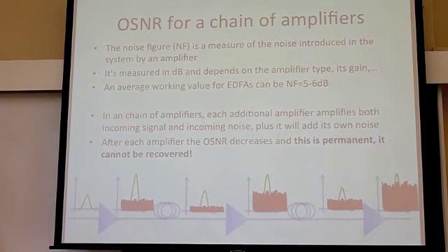The photons are generated here by the amplifier. So as you lose power here, you lose power there as well, which is a good thing. Then you amplify. So if this didn't introduce any noise, then you would go back exactly to this, and your signal to noise ratio would remain the same all over the place. It would be great. That doesn't happen. So you have the same situation as this, plus this amplifier adds its own noise.